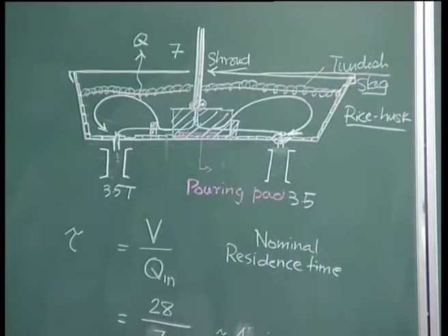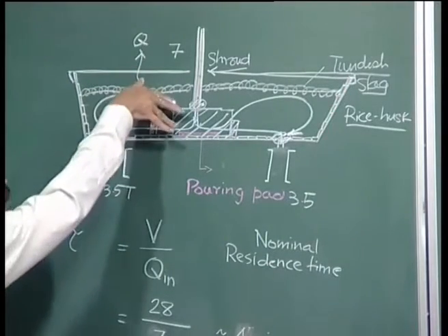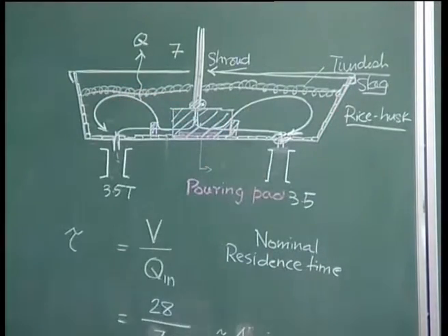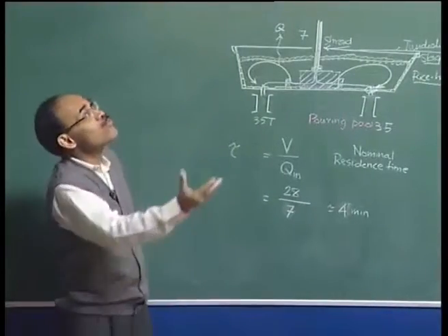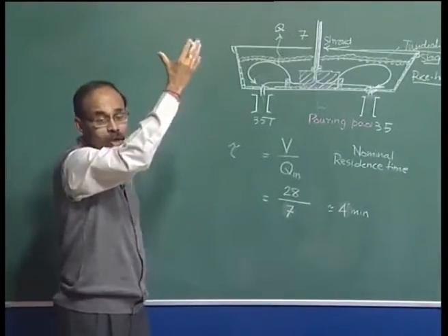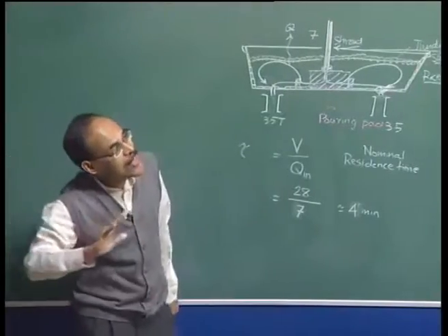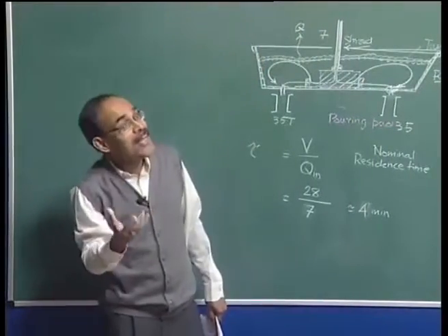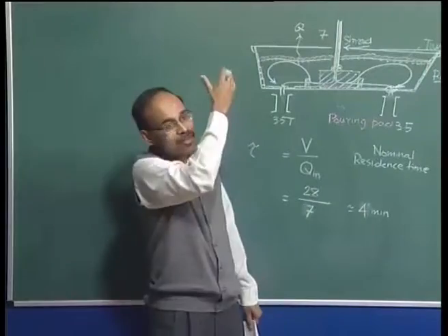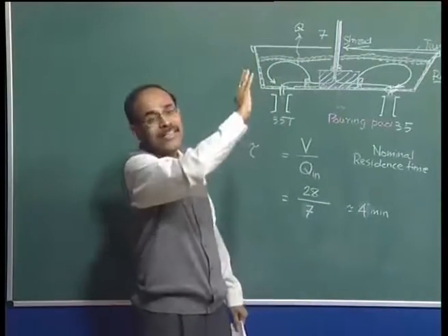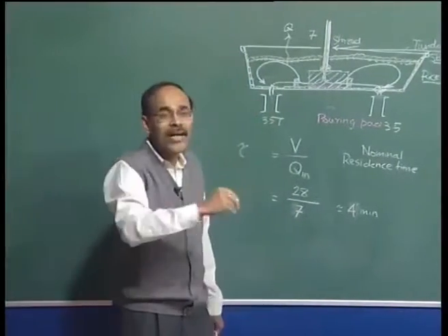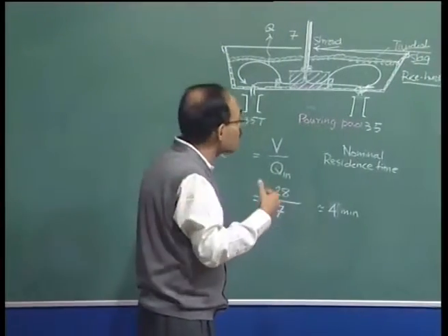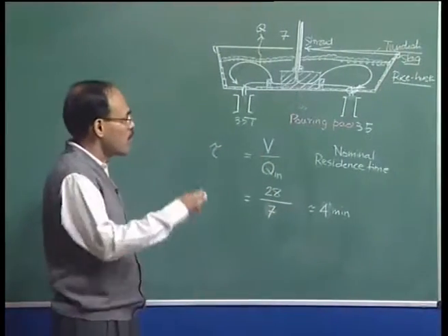We also want that the flow need not be going downward, because inclusions travel in which direction? Inclusions will travel in the upward direction. So, I should create a flow which itself is directed upward, thereby helping the inclusions. Okay, you guys go ahead, I am giving you some assistance with the upwardly directed flow, and as a result the inclusions will have a greater tendency to move towards the upper surface.